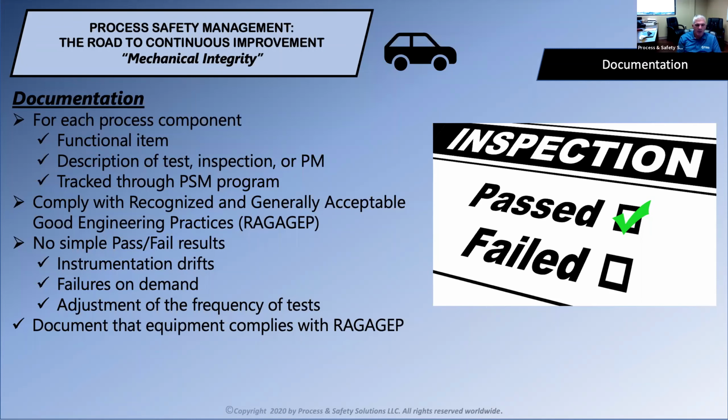So for every milliamp that you receive, you expect a linear response. Well, not all instruments stay linear, and that's one of the things that you're testing as part of your calibration, that you should be doing at least annually, or more frequently or less frequently, depending on the criticality of the device.